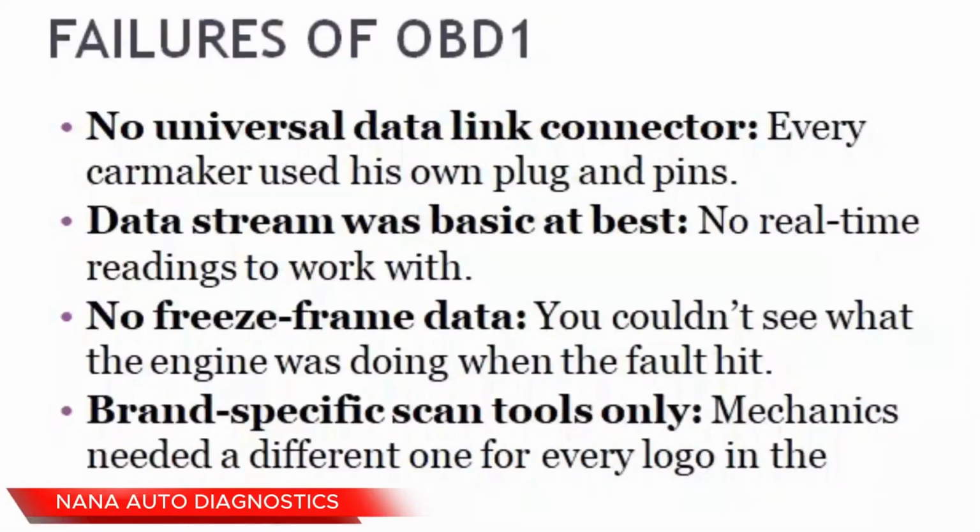So let's look at the failures of OBD1. No universal data link connector. As I told you earlier, every car maker used their own plug and pins and also scan tools. Now the data stream was basic at best. So this system did give real-time readings.